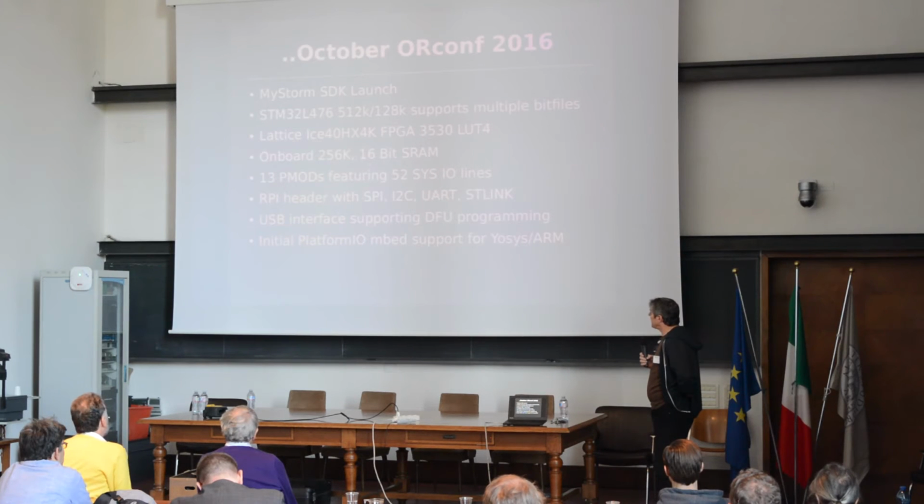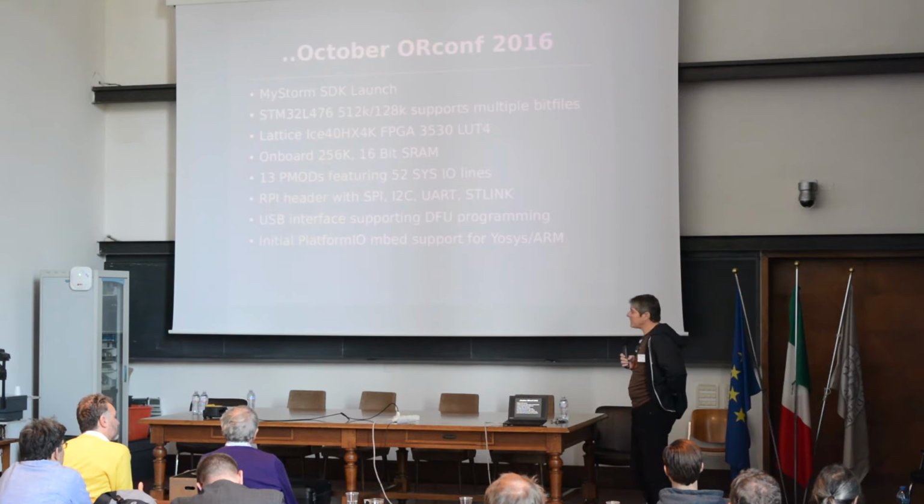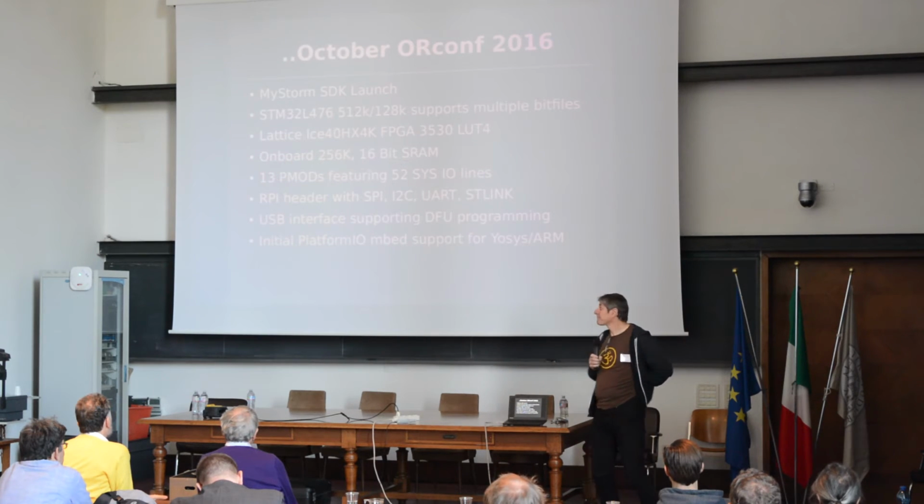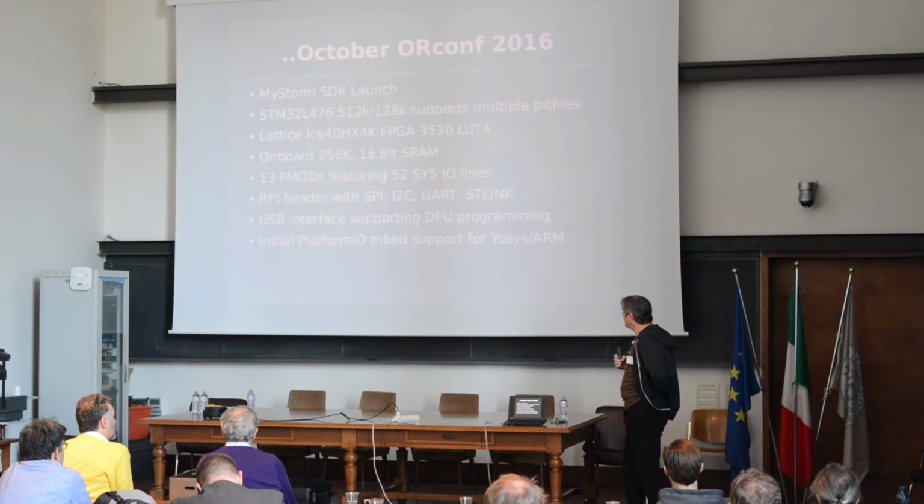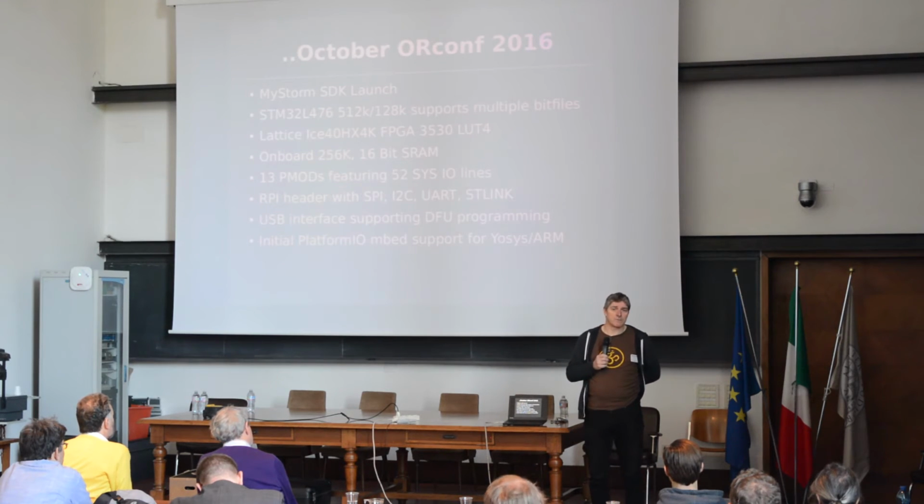The Lattice ICE40 that we're using is the HX4K. Now, even though that has 3,530 lookup tables, that we believe is constrained by the Lattice tools.